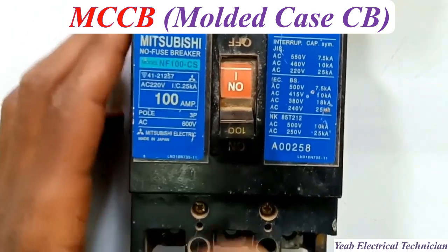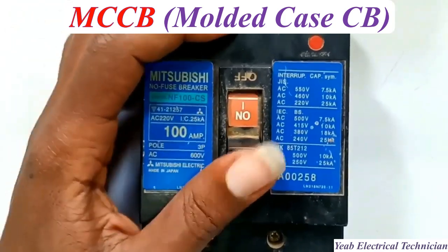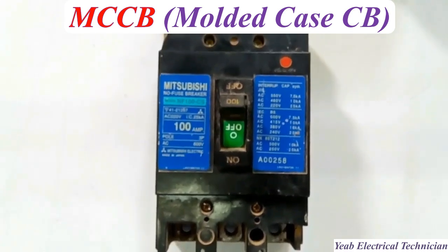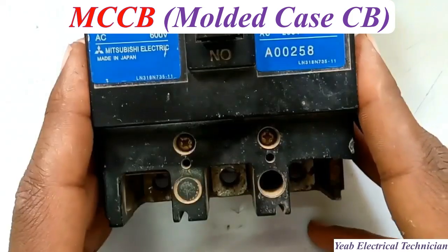For protecting against overloads, a thermal element, which is a bimetallic strip, bends when hit by a sustained overload current, triggering the tripping mechanism. And for protecting against short circuits, a magnetic element, which is a solenoid, is activated by the sudden high surge of current during a short circuit, causing an instantaneous trip.